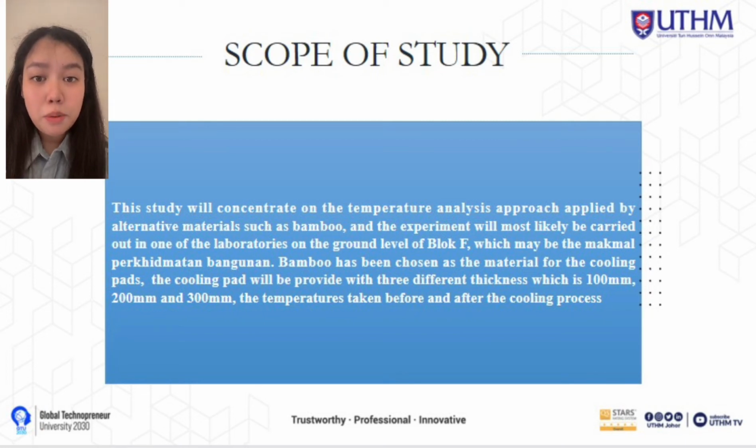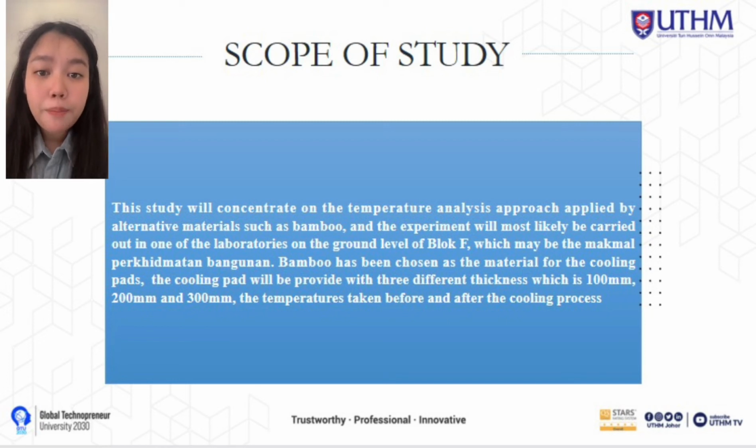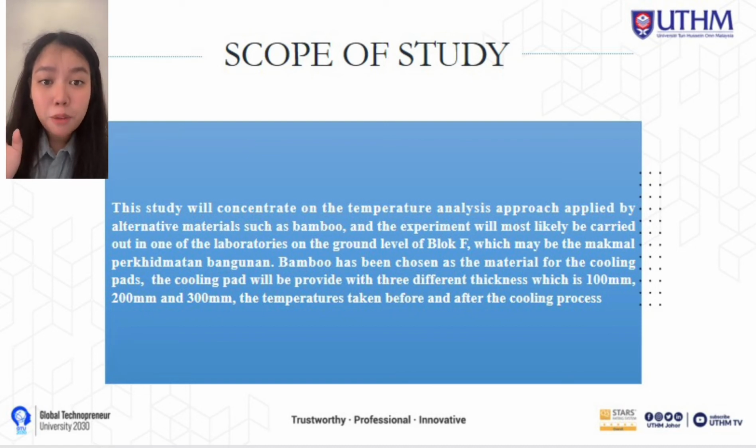In this experiment, the water usage of an evaporative cooler was lower by substituting the current cooling pad with bamboo pads. The evaporative cooler usually has three main parts, which are a fan, a pad that holds the liquid water, and a pump that brings the water to the pad. The fan is used to pull warm air across the pad and then move it around the building being cooled. The pump sprays fresh water onto the water-carrying medium as needed to keep the system from drying out.